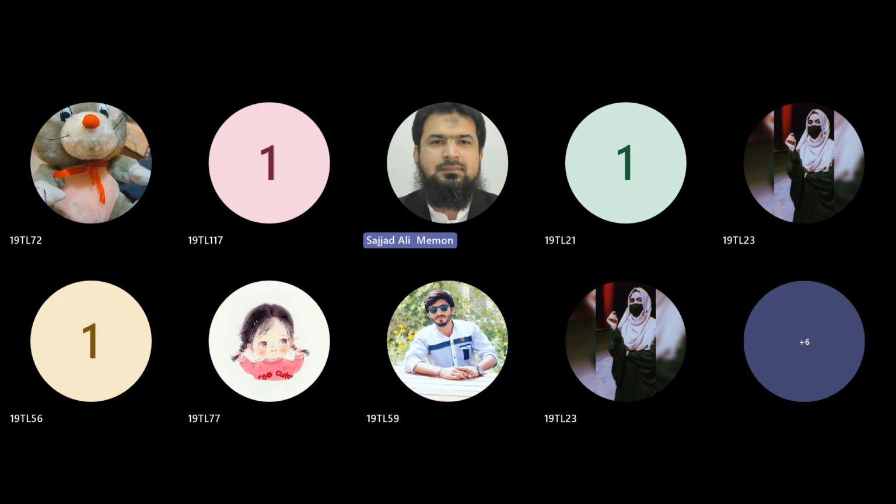So in the alpha beta formula, this minus sign will be same as in the equation here. This minus sign and this minus sign will be the same, whereas it is reversed in the cos alpha and beta formula. So here it is sin alpha, alpha is omega ct, minus beta is 135. So this is how we convert a quantity given as minus cos omega ct minus sin omega ct to 1.414 sin omega ct minus 135, where 1.414 is the amplitude and this is the phase shift in the carrier.